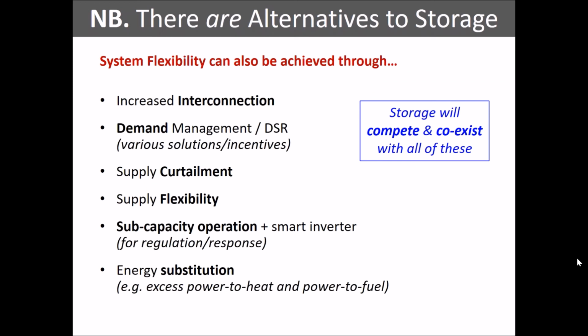Where storage comes into play is that when the wind is blowing at full tilt, rather than upgrade that power line, there potentially also becomes a point where it's cheaper to build storage at the wind farm, put the energy into your storage, and then you can, if you like, let it out through your grid capacity at a slower rate, so you don't exceed the capacity on the power line. So that's one example.